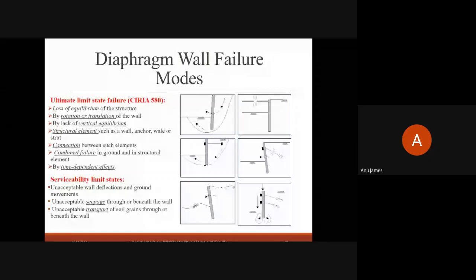if we underestimate or make any miscalculations about the axial forces that can act on the system. The failure of different supporting structural elements, such as an inclined strut or even the wall element. And similarly, the connections between these different supporting elements such as struts, walers, etc. If the connections are improper, it may lead to the structural collapse of the entire system.